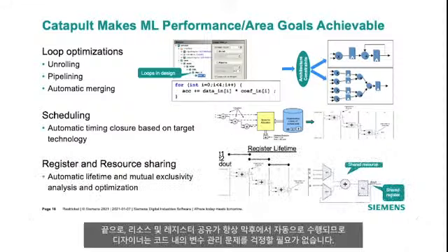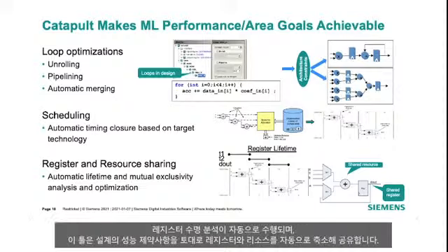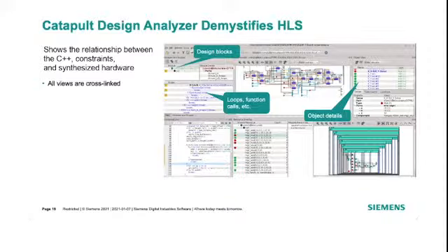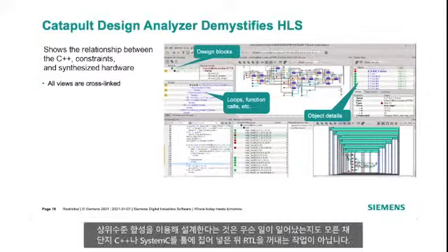And lastly, automatic resource and register sharing is always performed under the hood, so designers don't need to worry about managing variables in their code. Register lifetime analysis is performed automatically, and the tool will automatically reduce and share both registers and resources based on the design's performance constraints. Designing using high-level synthesis is not just taking C++ or System C, throwing it into the tool, and getting out RTL without